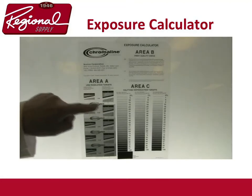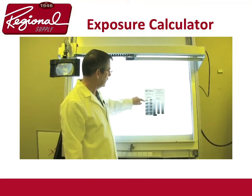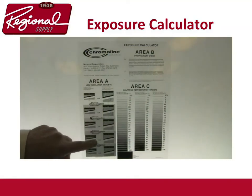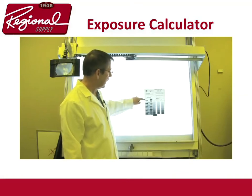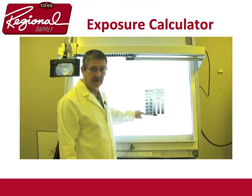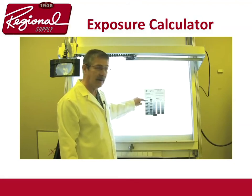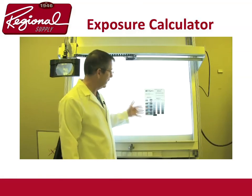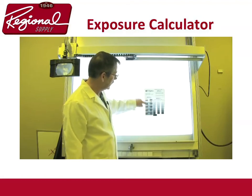Also, if you notice, we have two sets of targets. And these targets are designed for mesh counts. Also, in the middle, we have these numbers, 1.0, 0.7, 0.5, 0.33, and 0.25. If you notice, it gets from light to dark. It's actually blocking more UV as it gets down farther. The more UV it stops, the shorter the exposure will be, and the more it goes up, the more exposure. So with one exposure, you get 5 exposures at the same time. This is going to speed things up for you. It's also going to determine what your proper exposure is. What you want to aim for is one of these targets.